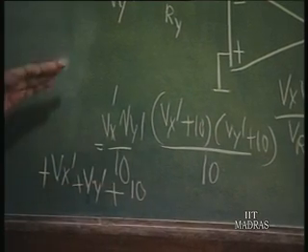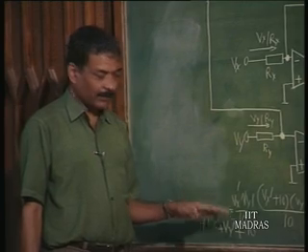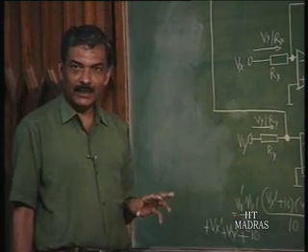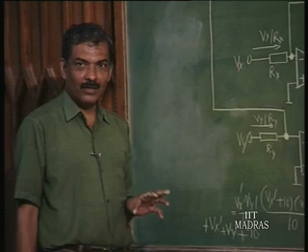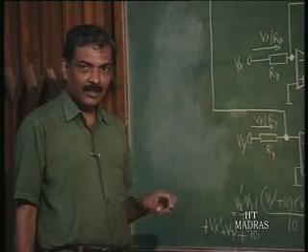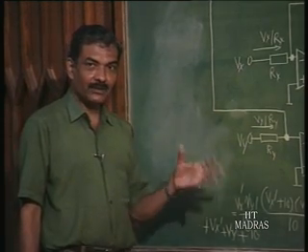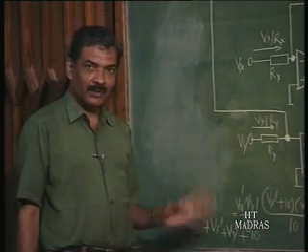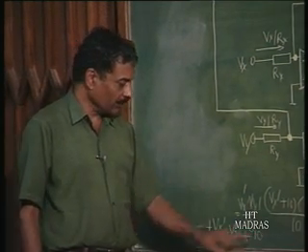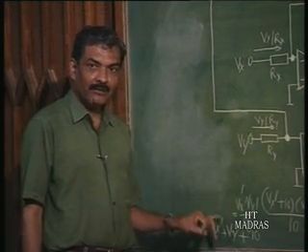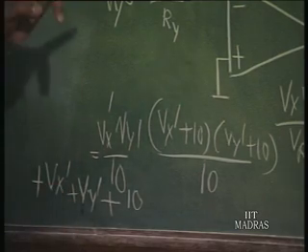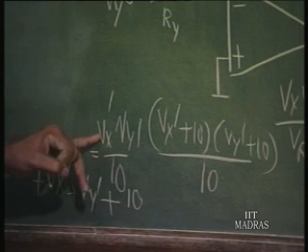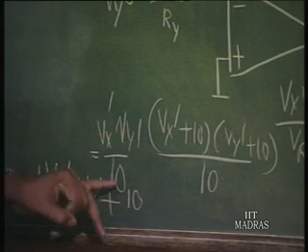This can be deducted from the total output of the multiplier by using another operational amplifier, which we know how to design, because in our earlier discussion we have discussed how to design an amplifier which will subtract whatever voltage you want from the output. So, the offset can be removed, the x feed through can be removed and y feed through can be removed. So, the output of that op amp, which is subtracting all these things, will be giving you the 4 quadrant output Vx' Vy' by 10.